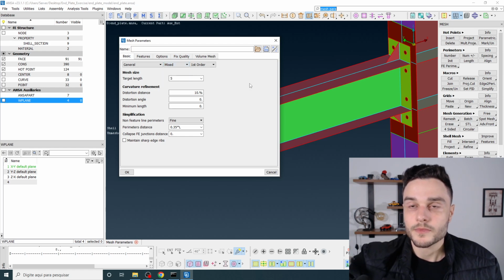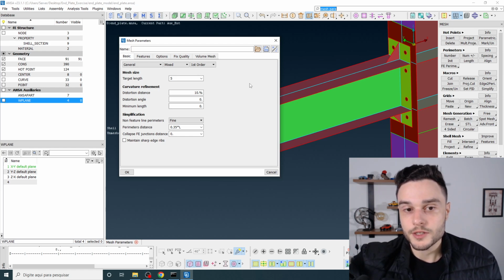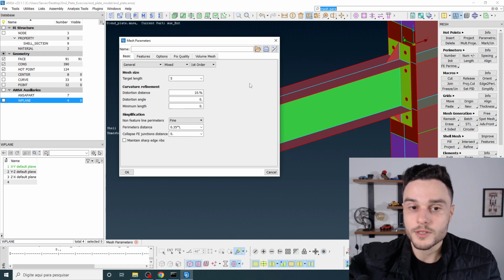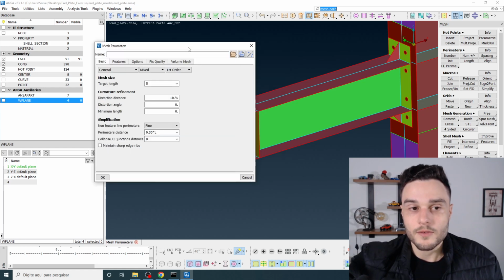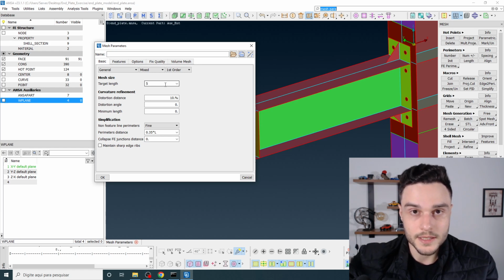You know that we should try to avoid triangles in a shell mesh, because triangles are not good. You know, shell meshes are linear elements, right? We have, for example, for the quadrilateral element, 4 nodes, and for the triangle, 3 nodes. For that reason, and we also know that in the formulation of the shell elements, we have a mix of the plane stress element and the plate element.